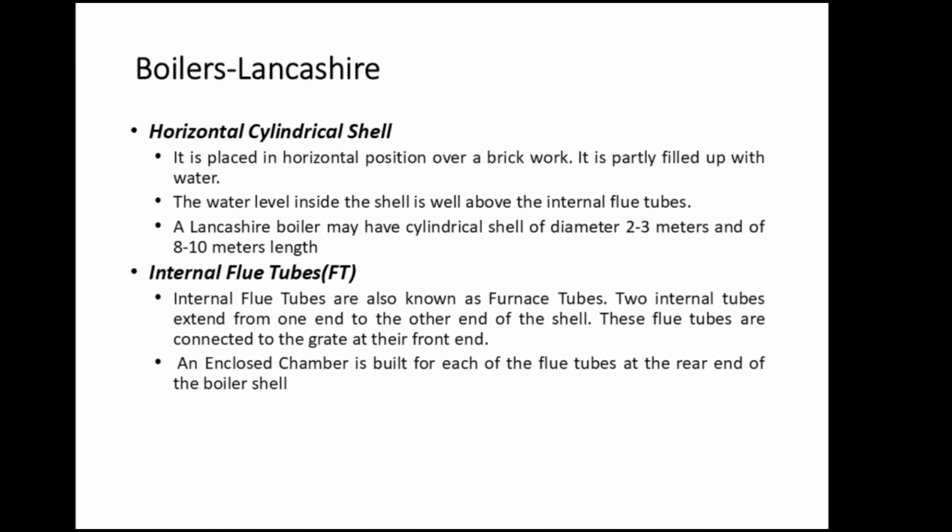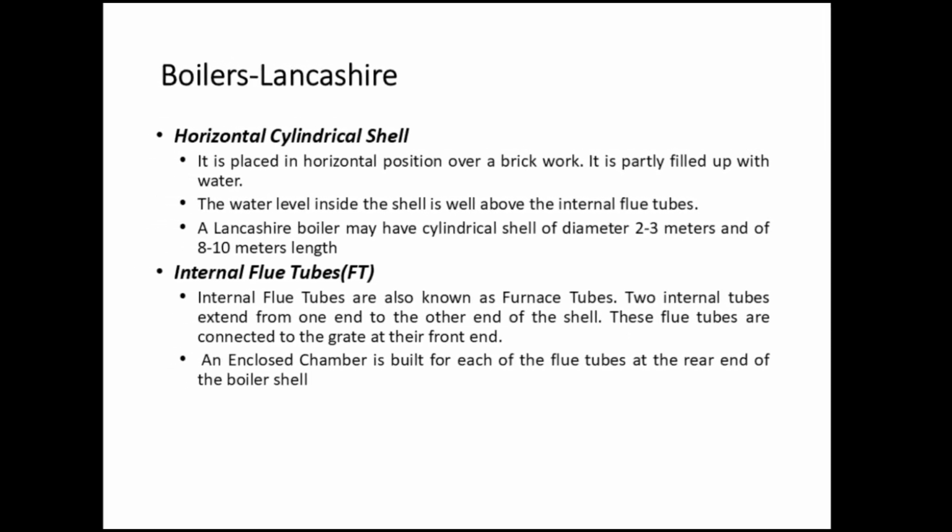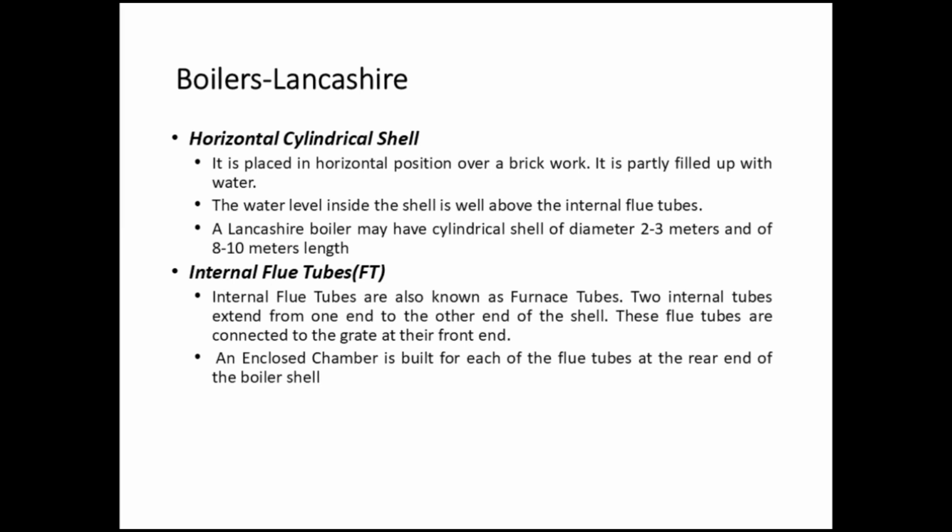Boilers, Lancashire, horizontal cylindrical shell. It is placed in horizontal position over a brickwork. It is partly filled up with water. The water level inside the shell is well above the internal flue tubes. A Lancashire boiler may have a cylindrical shell of diameter 2 to 3 meters and of 8 to 10 meters length.